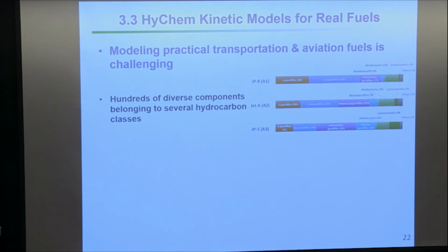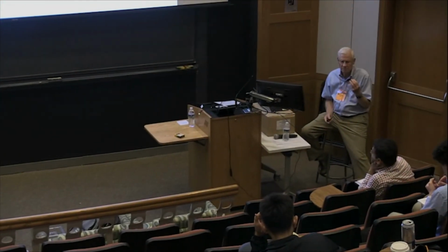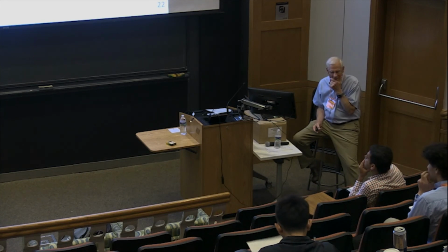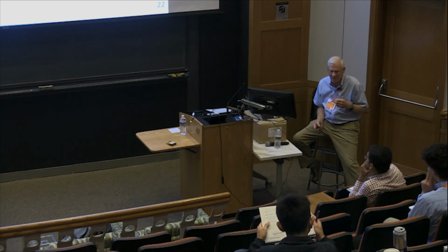So typically what people do is they will say, well, or maybe they do gasoline. Maybe I could represent gasoline by 3 surrogates. I might pick 3 hydrocarbons that behave kind of like gasoline, and I would pick them so that they would match certain properties. Maybe they would match the ignition delay time. So maybe I would find that if I blended 3 things together in certain proportions, they would match the ignition delay time. Then I'd look and say, well, the trouble is it doesn't quite match the CH ratio.